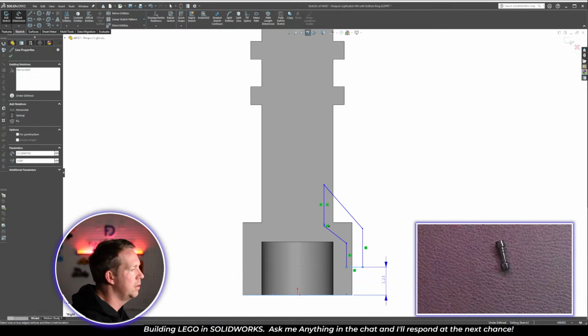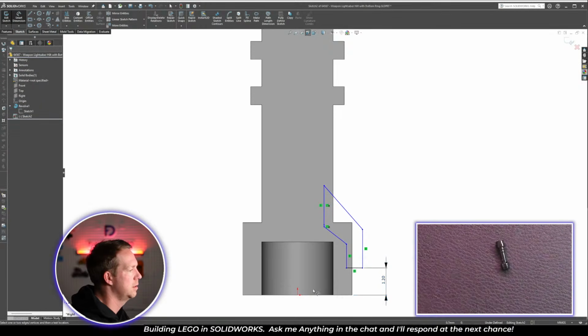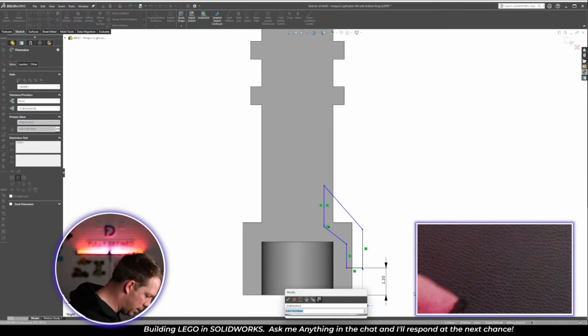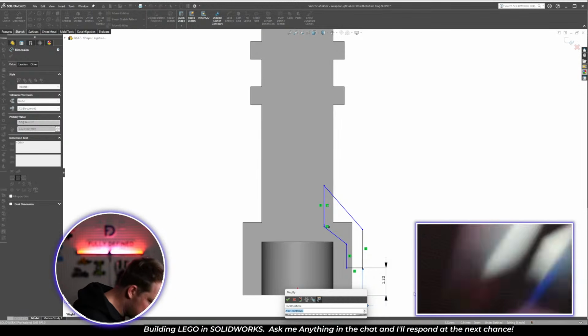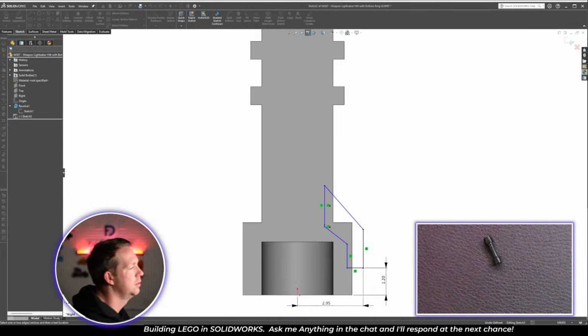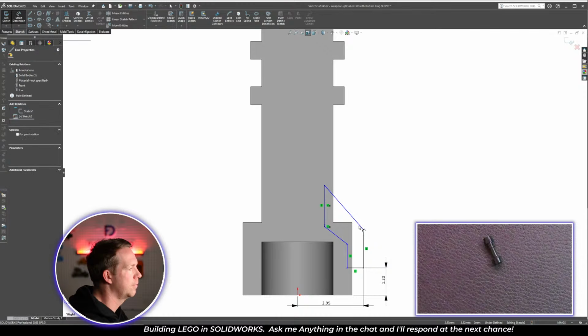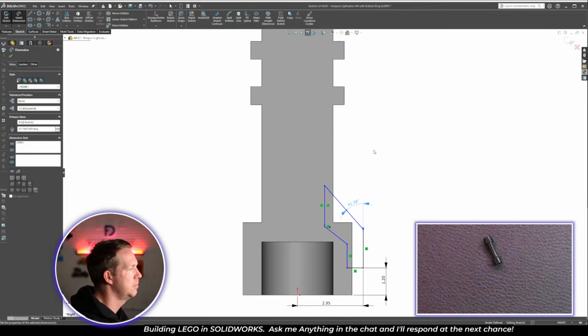So now we've got the rough appearance. Let's put in some dimensions, get it fully defined. Use our origin as a reference. I can measure how big it is outside to outside. This is 5.9. Would make this 2.95. I think it looks like a 45-degree angle.